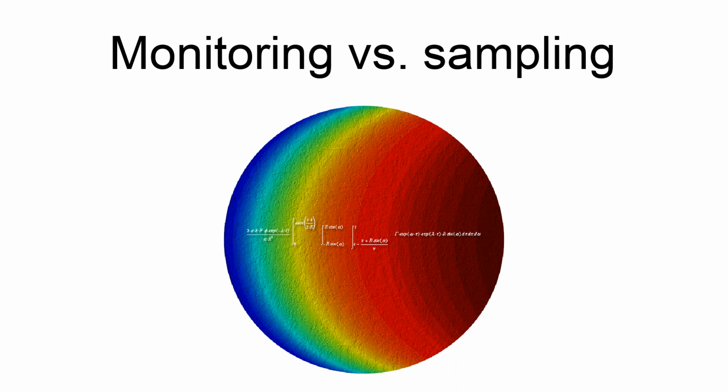In general, sampling has better detection sensitivity for low levels of airborne radioactivity, due to the much larger total volume of air passing through the filter medium over the sampling interval, which may be on the order of hours, and also due to the more sophisticated forms of quantitative analysis available once the filter medium is removed from the sampler. On the other hand, monitoring with CPAMs provides nearly real-time airborne radioactivity level indication. It is common practice to refer to sampled air even when discussing a CPAM, i.e., as opposed to monitored air, which would, strictly, be more correct.